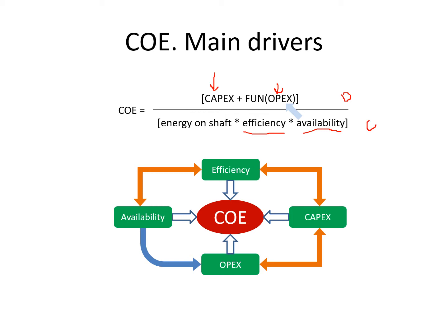At the bottom here we have all the energy which will be produced throughout the lifetime of the wind park. So we see that efficiency of the components will play an important role here. If our wind turbine generator is not efficient, then the park will produce less energy than it would have produced with a better generator. Availability is like a derivative of reliability. Availability says for how long, out of the overall time of the existence of the system, it is available for generating electricity.